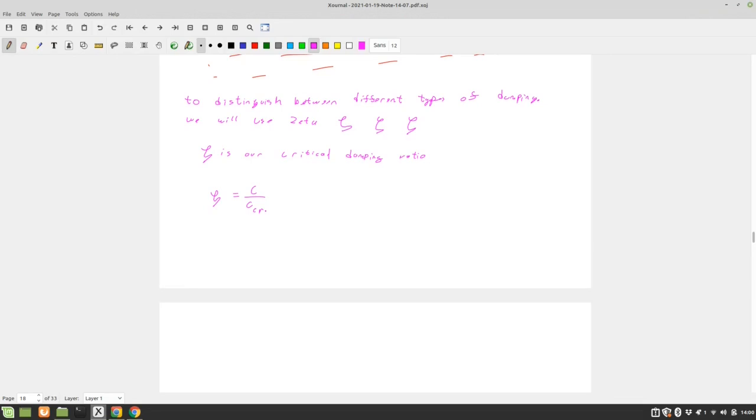So if this value is equal to 1, what do we have? Critically damped, right? And if it's greater than 1? Overdamped, yeah. If it's less than 1, underdamped. I think that's right. This process is just normalizing the damping, putting it as a variable. Yeah. So it's normalizing the damping and allowing you to have a variable that in an engineering meeting type, both